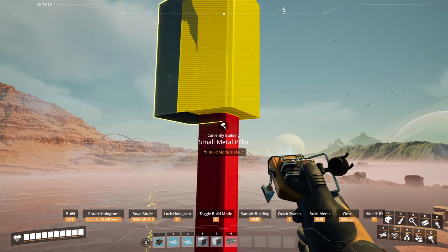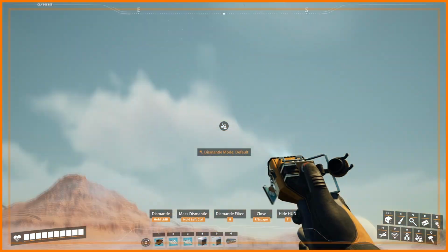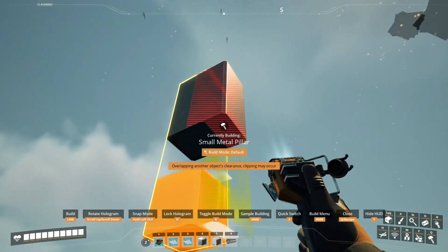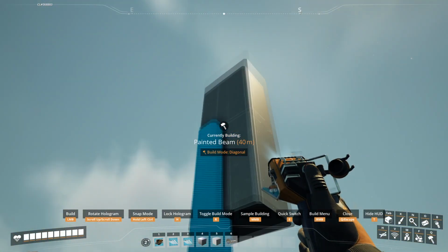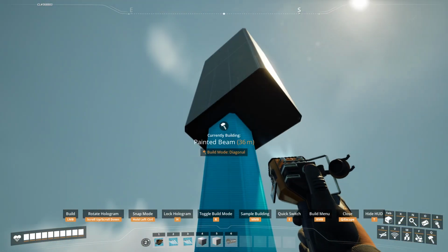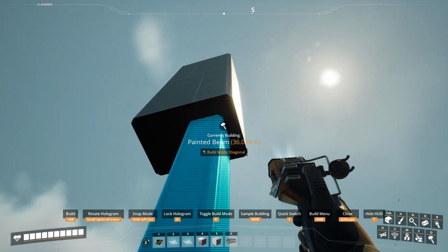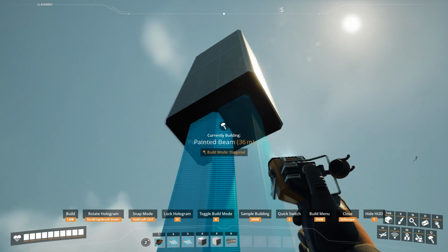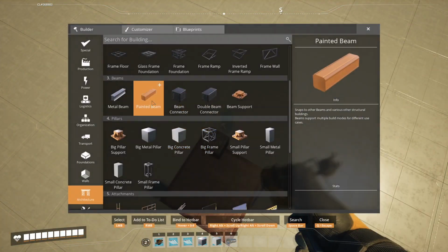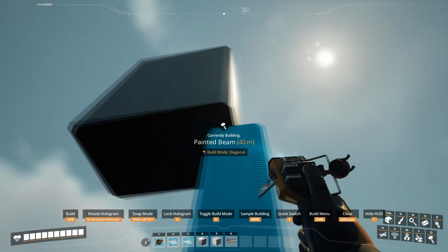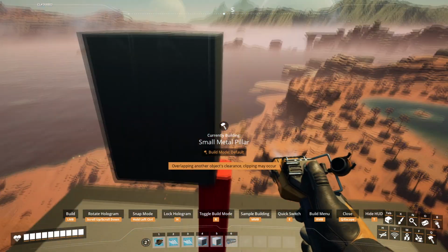And the reason why you always take the beam out to full length is if you bring it in slightly, let's see if I can demonstrate here. There, this probably would be the same length, so that's 36 meters. But if I bring it across, can you see it starts changing, 36.056? That's not what we want. So that's why we take it out full length. So go up there, up, and then snap to the edge of that, and then pillar on the end.